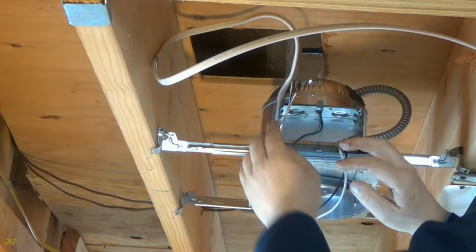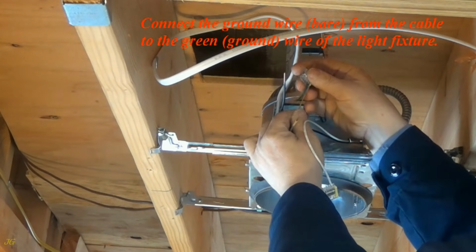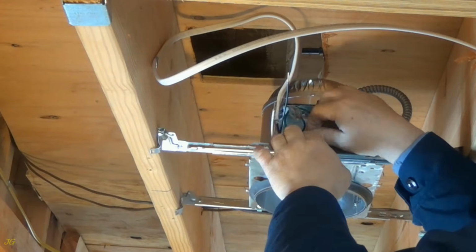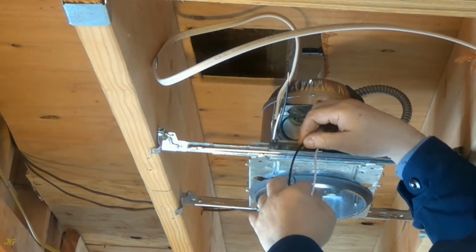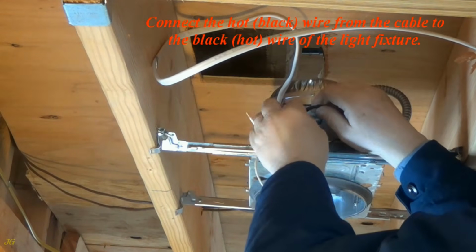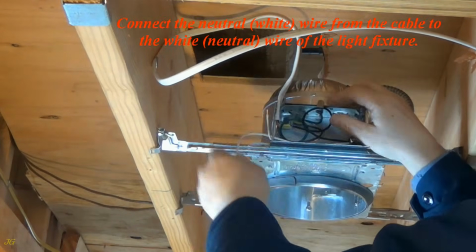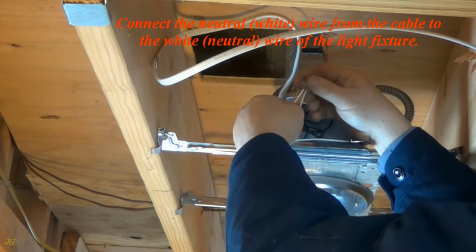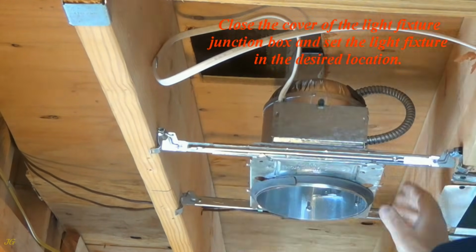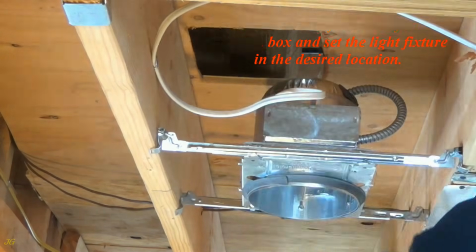Connect the ground wire, bare, from the cable to the green, ground wire of the light fixture. Connect the hot, black wire from the cable to the black, hot wire of the light fixture. Connect the neutral, white wire from the cable to the white, neutral wire of the light fixture. Close the cover of the light fixture junction box and set the light fixture in the desired location.